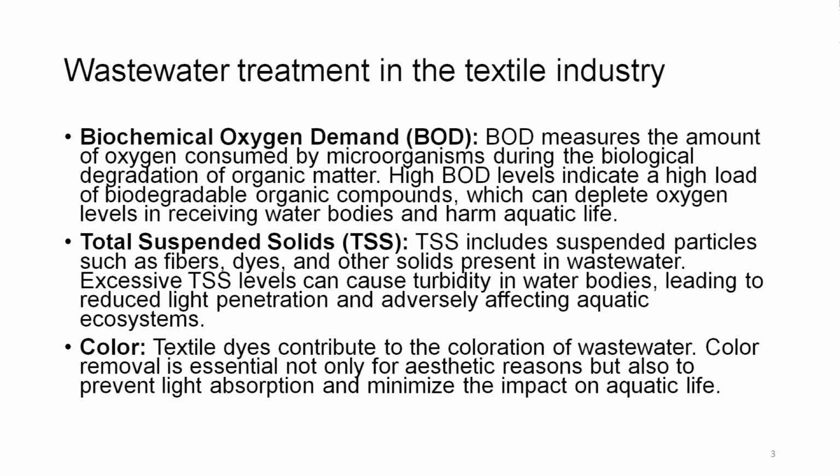Biochemical oxygen demand or BOD. BOD measures the amount of oxygen consumed by microorganisms during the biological degradation of organic matter present in the textile effluent. High BOD levels indicate a high load of biodegradable organic compounds, which can deplete oxygen levels in receiving water bodies and harm aquatic life.